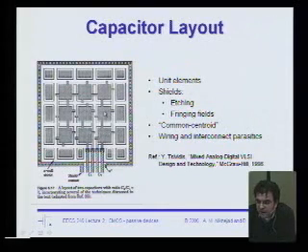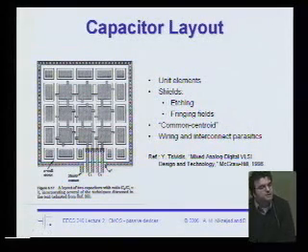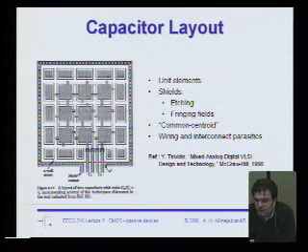And the reason I do that is that I want to do a unit cell design where I have this capacitor and this capacitor, and I want their ratios to come out very accurately. I want to get rid of systematic errors. So if I don't have these little, let's say, stubs on this guy, which doesn't need to connect, then I would get a systematic error. But here, by having this stub, I can either connect it or not connect it, and I'll get an extra capacitance due to that stub, but that's part of the design. So it's a very nice way of doing the layout.